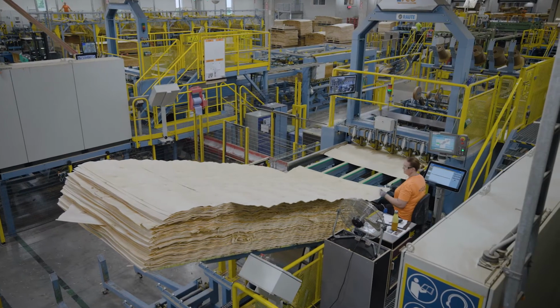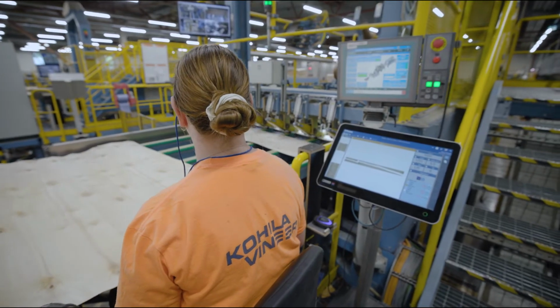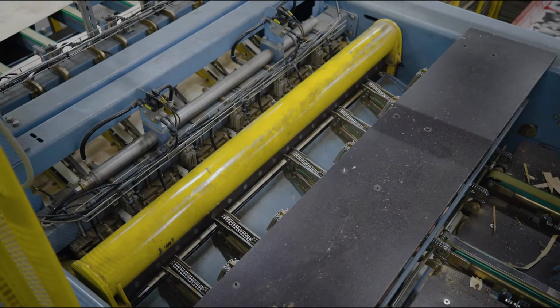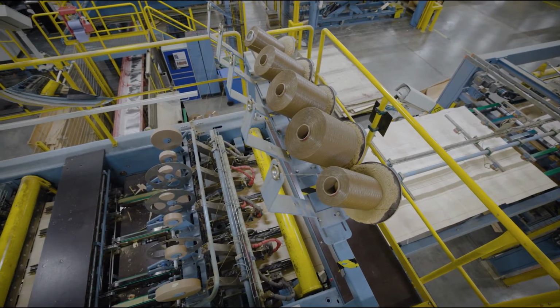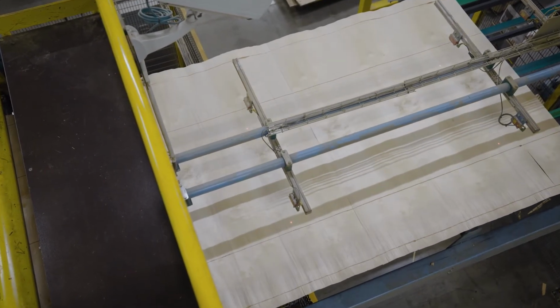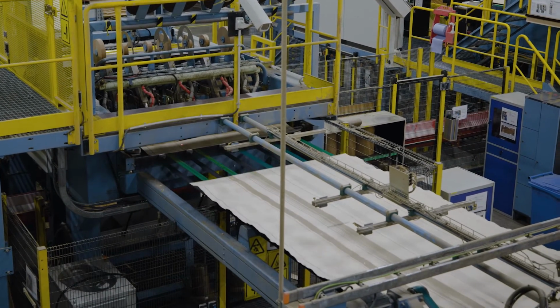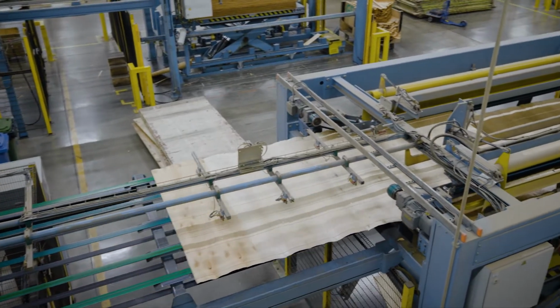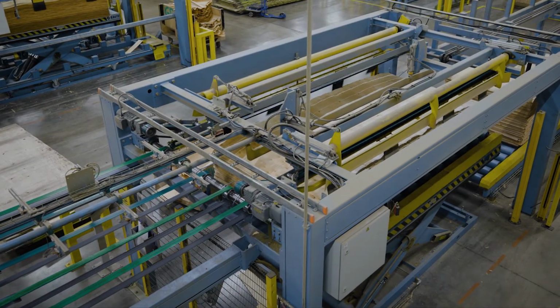In core veneer composing, random strips of veneer can be composed into full-size veneer sheets used inside the plywood panel. Butt joints ensure the composed veneer sheet's quality while remaining invisible. Core veneer composing is one of the best ways to utilize all raw material instead of chipping them to pulp or energy.